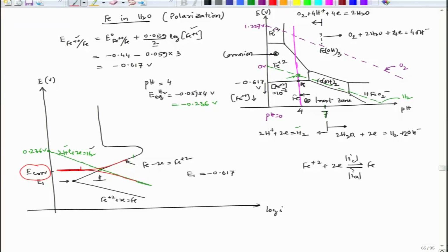So, beyond this, as we go ahead, we could see that we are only considering I_A, because the current density corresponding to I_C is very low compared to I_A. This is basically nothing but I_A. Okay. So, now it is reaching I_critical. Now, I_critical is the point where maximum dissolution takes place, and beyond I_critical, if we increase the potential further, my I_A is reducing to a great extent.